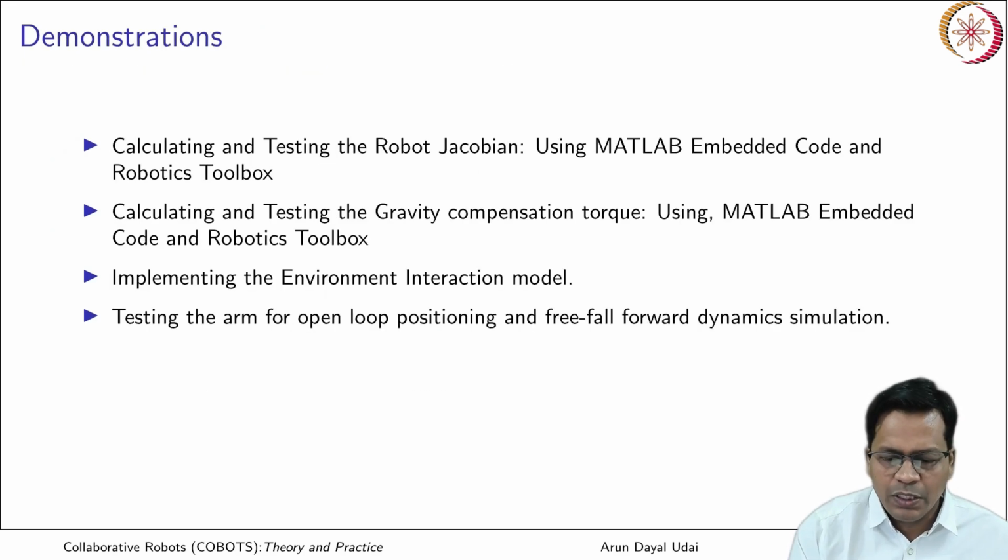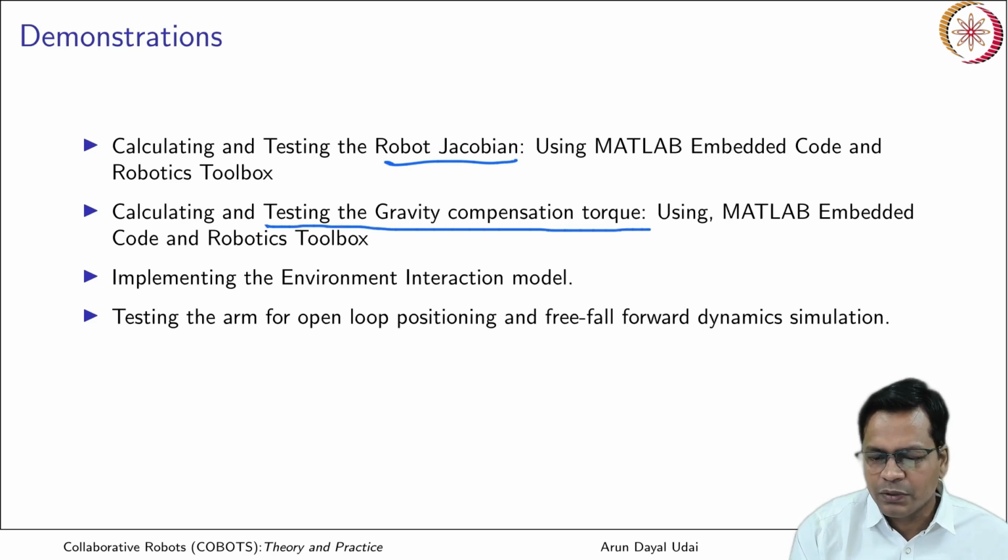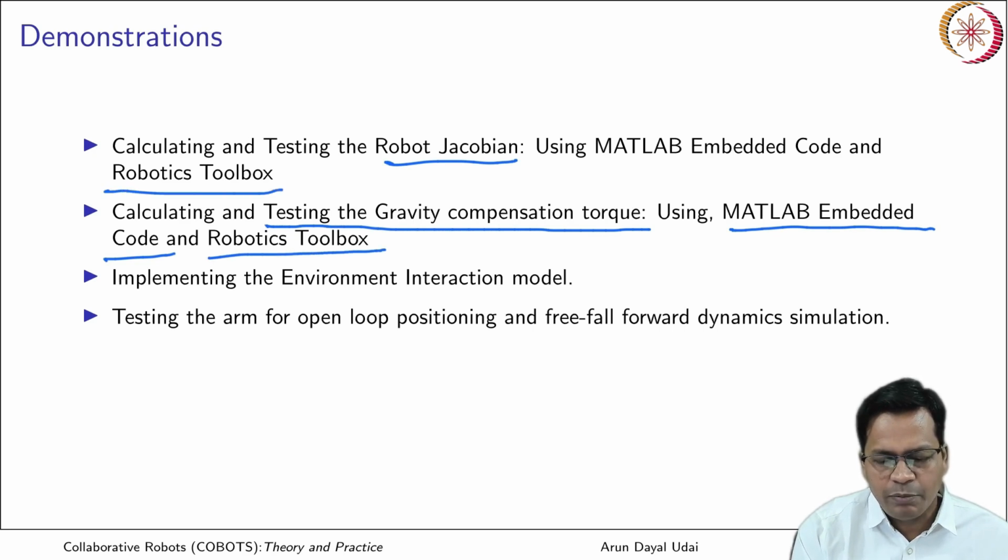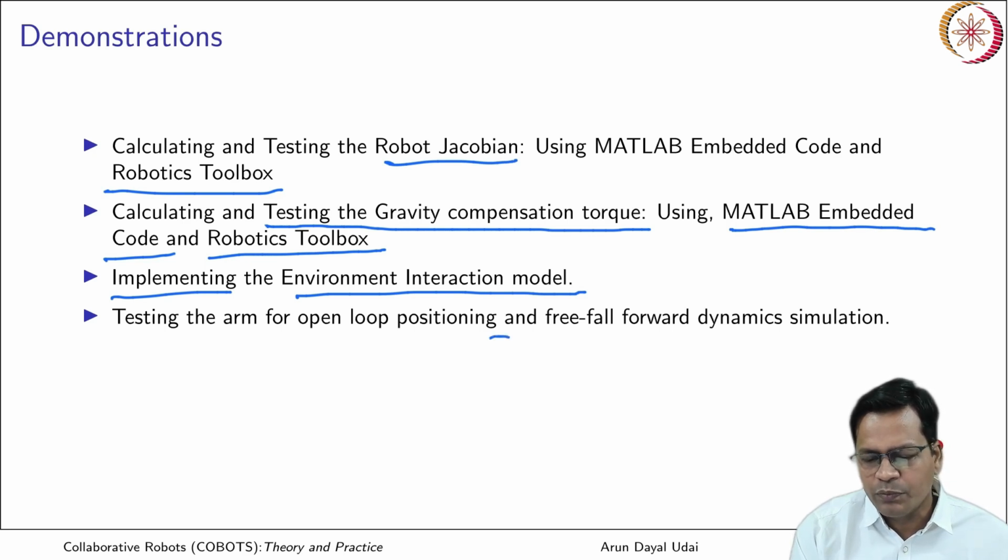Later, we will also see a demonstration of calculating and testing the robot Jacobian, which I'll be doing in the next module. We will also calculate and test the gravity compensation torque, using MATLAB embedded code and also the robotics toolbox. I'll be implementing an environment interaction model. All this I'll be doing in my next lecture. And finally I'll test the arm in open loop positioning and do a free fall forward dynamics simulation.